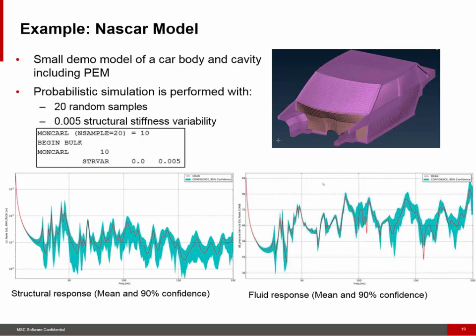And then you can post-process the probabilistic results, like the mean value and confidence interval, 90% confidence, both for structural and in this case also for the fluid. So it shows that already from fairly low frequencies there's a significant influence from the variability on this particular model.